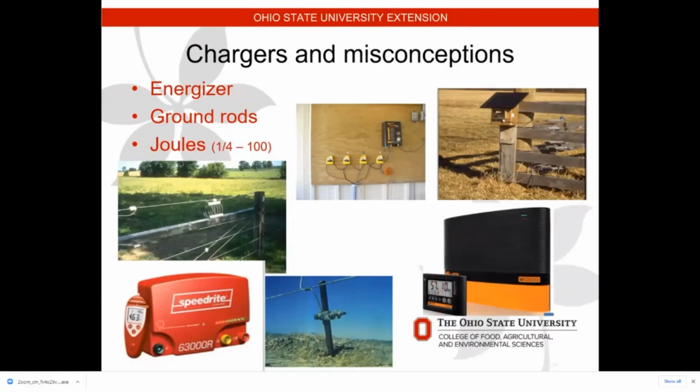But these chargers and other companies have them where you can get a tester with them. You can lay this metal piece here on the end right on the fence and it'll tell you which direction the fault is. Another feature that I like, some of them have, you can lay it on your electric fence, push a button, it'll turn your charger off, make your repairs, fix your fence, do whatever you need to do, then put it back on there and turn it back on if you happen to be on the back 40. I think that's pretty slick.